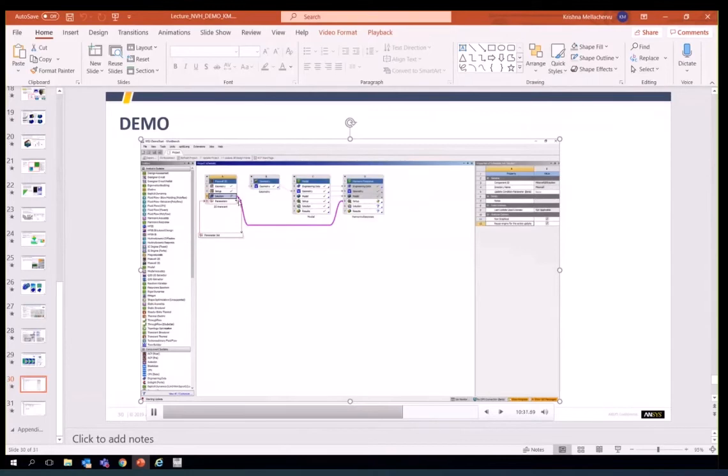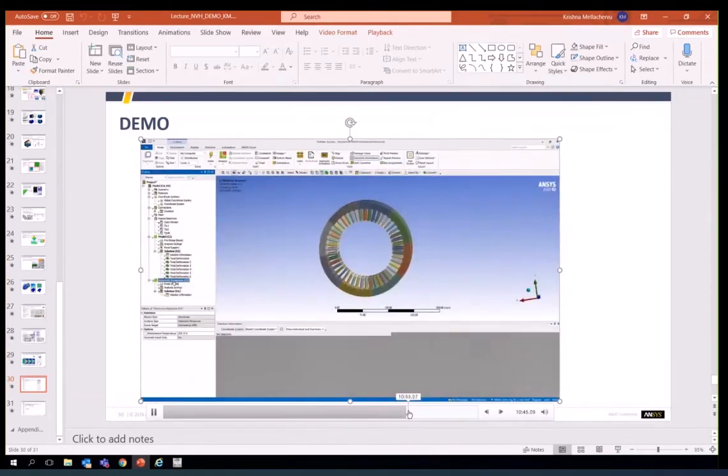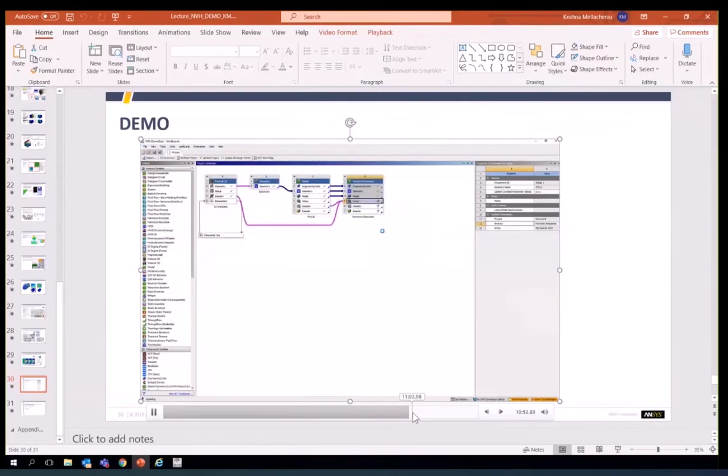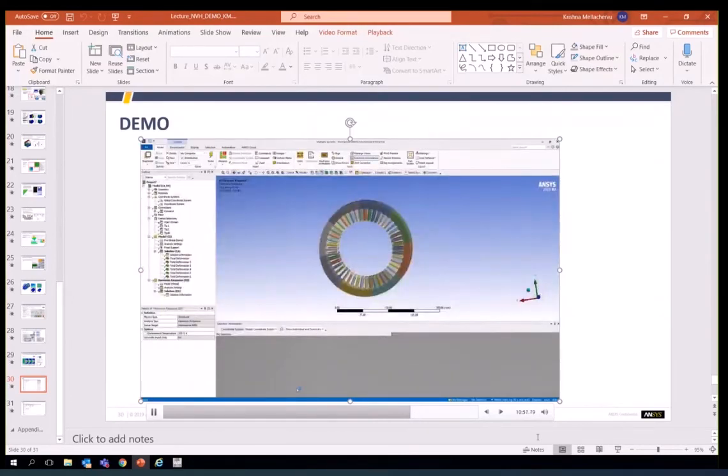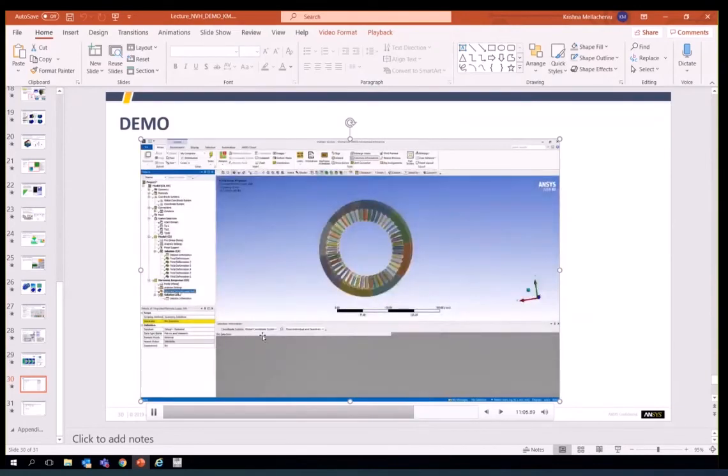But before we do that, we need to drag and drop the solution onto setup, and that is what carries the forces and maps it onto the structure. So we are going to update the model, and once we update the model, we'll be able to see the imported remote load folder.